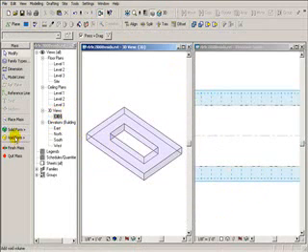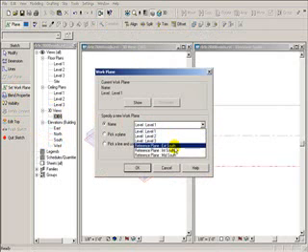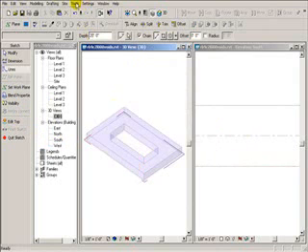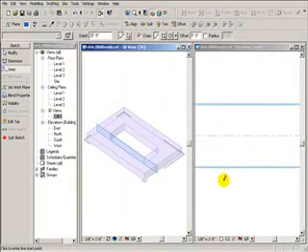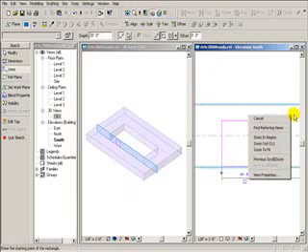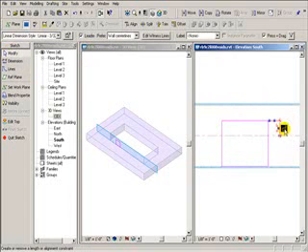And I'm going to start my void blend. I'm just going to set my work plane, and my work plane will be the interior south. I'm going to turn visibility on in this view. And I can start my sketch. I'm just drawing in something rough. I'm going to lock that dimension.